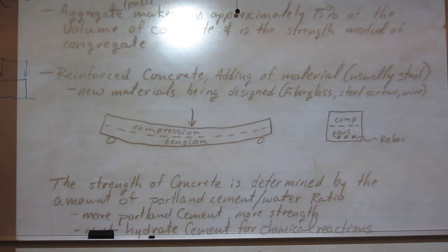But if that's 10 feet, 10 divided by 240 would be what, 0.24? Okay, so on a 10-foot device, we're going to allow about 1/4 inch of deflection on the whole thing, maximum. 1,000 feet, that would be 24. Okay? And it's still going to hold together.